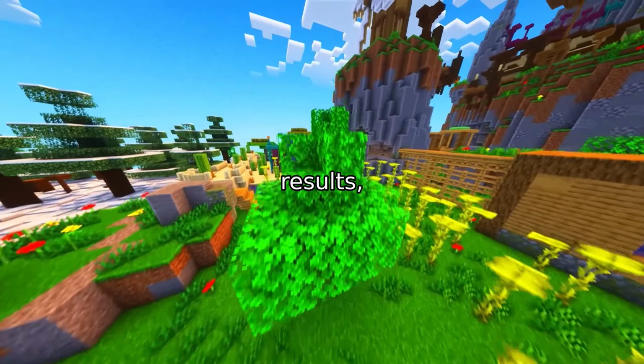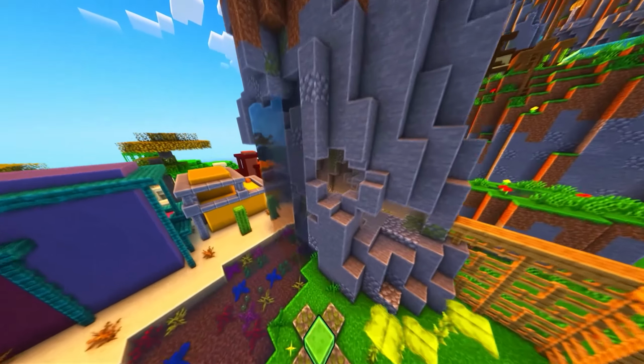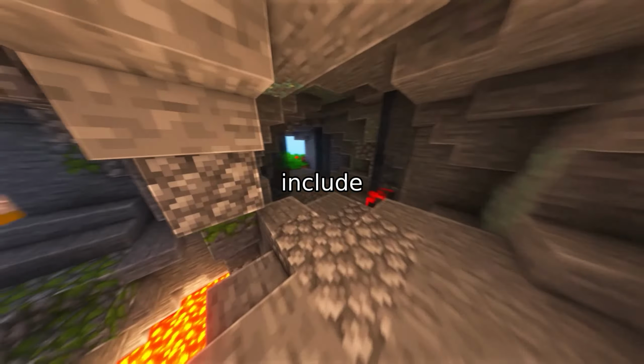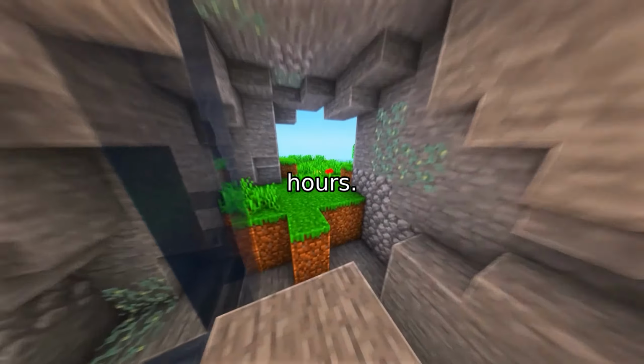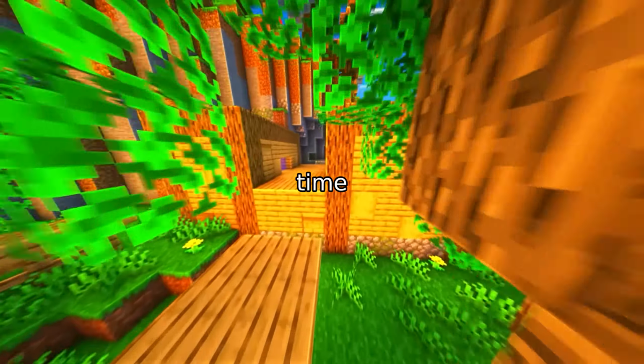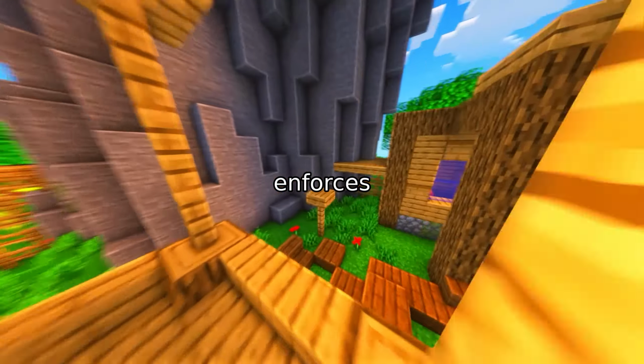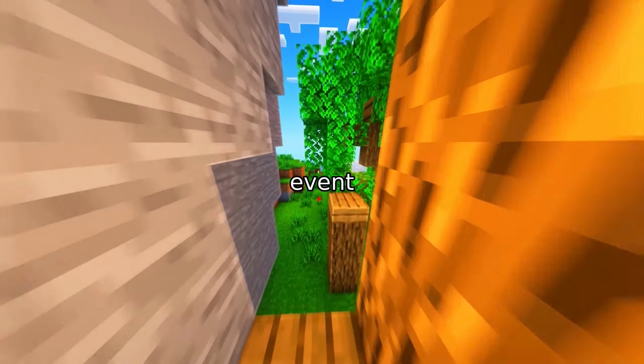Now, real-world results, two industrial case studies. Case 1, battery production demand response. We modified the objective function to include incentive-based load reduction during peak hours. The generated code dynamically calculates energy consumption per time slot. Adds an incentive reward term based on load reduction. Enforces a minimum reduction of 10 kW during the event window.